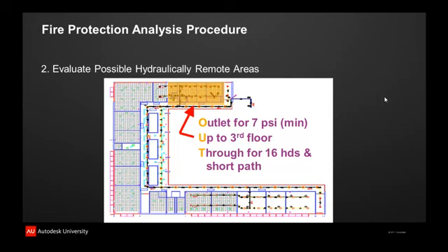The outlet pressure in this case is less than the first one we considered, the elevation the same, but this friction loss based on 16 heads could potentially be more than the friction loss for that longer path. The additional flow for 16 heads causes a greater friction loss. In fact, all other things being equal, 16 heads would have almost 4 times as much friction loss as 8 heads.